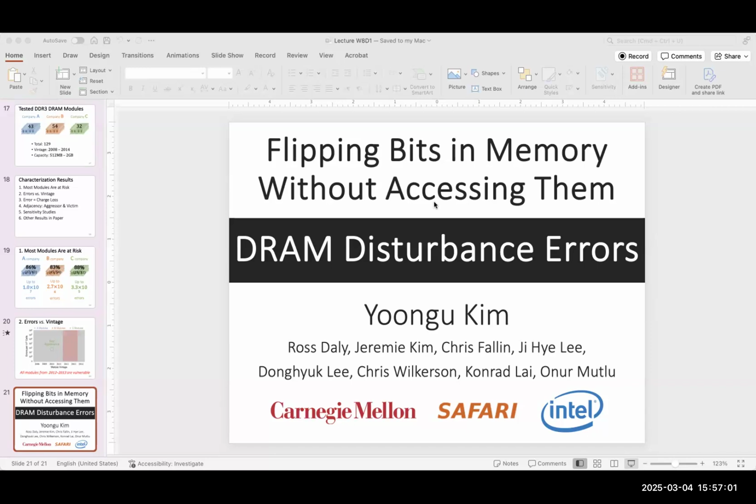So, high output voltage is the minimum output voltage on the output of a transistor that is guaranteed to be placed on the output for logic 1. So if we are saying that we are having logic 1, we are guaranteed that on the output we will have the minimum value of this output voltage. And this voltage input high is the minimum input voltage that is required to be interpreted as logic 1. And noise margin is what? The difference of these two. High output voltage minus input voltage high.